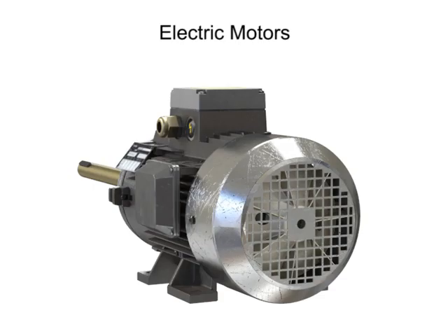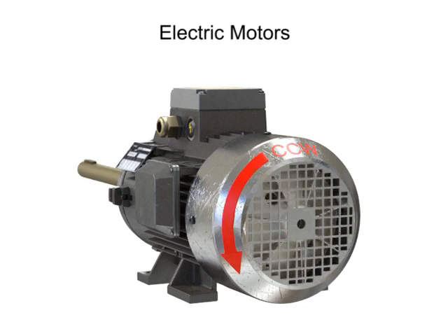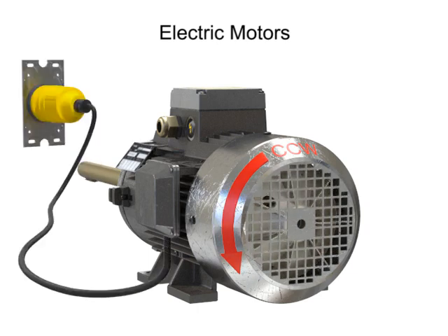There are many types of electric motors used for a variety of purposes in commercial industry. One critical task that must be performed prior to installing a motor is determining the motor's correct rotational direction. If a motor is required to rotate in a specific direction, it will have a direction arrow prominently displayed on the frame. But with few exceptions, most three-phase motors are made with symmetrical parts so the motor can rotate in either direction.